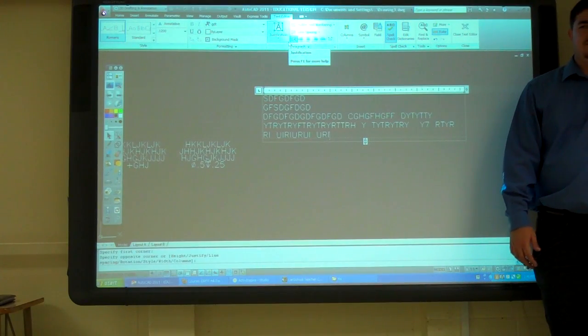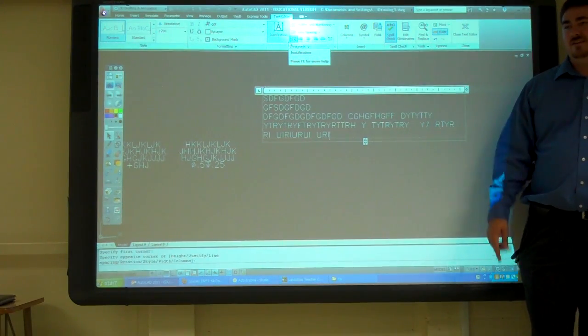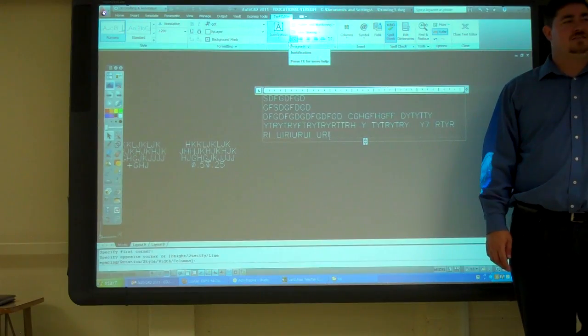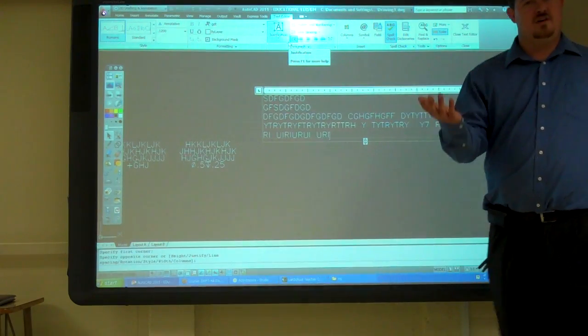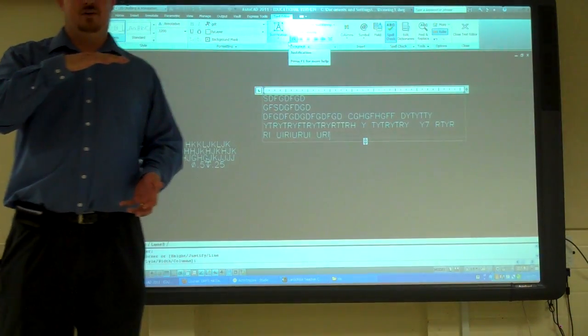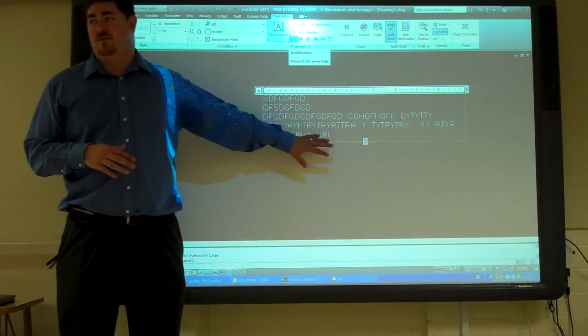So what do you think this is really good for? If you want a box around it. No, because it doesn't actually draw the box around it. You've got a lot to say. You've got a lot of stuff. So, like on architectural drawings, they have pages full of notes for you to read. I'd use MTEXT for that.